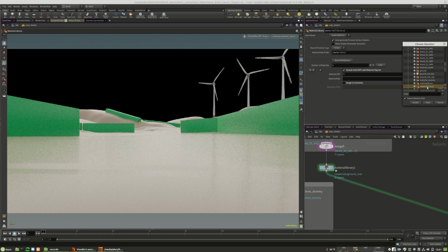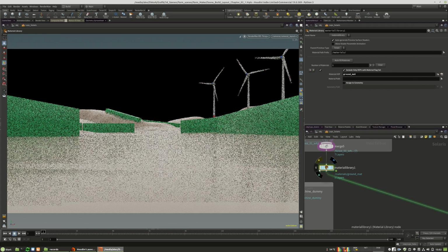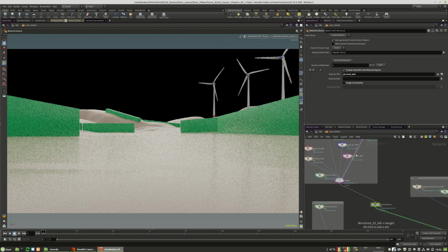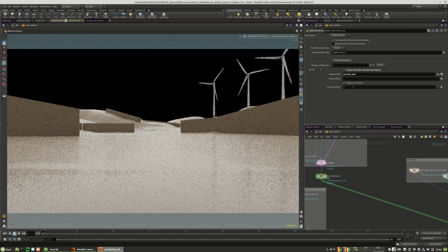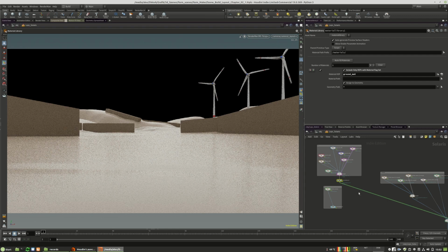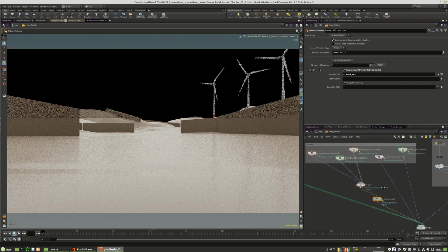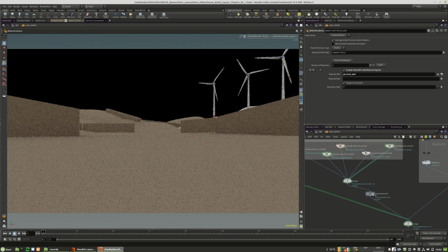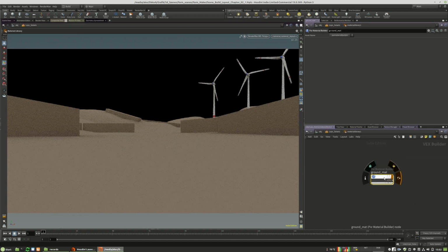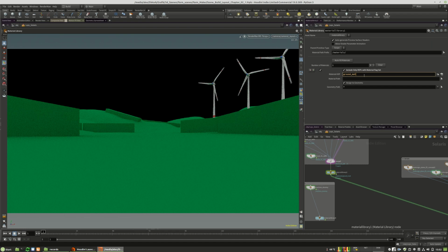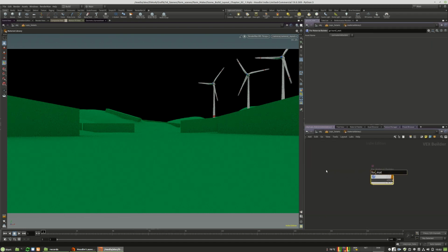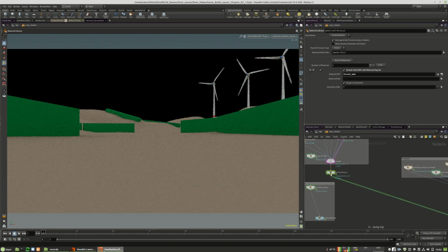Material library 1, where is it? Right in here. And it should be applied to all these objects right in here. So I put the asterisk into it, and so those are our trees. Of course, we can copy paste this, same procedure as here. This is our environment, and this should be brown, something like that. And here we go back and make it green so that we know that this is ground material forest material. So now you see the naming is important.